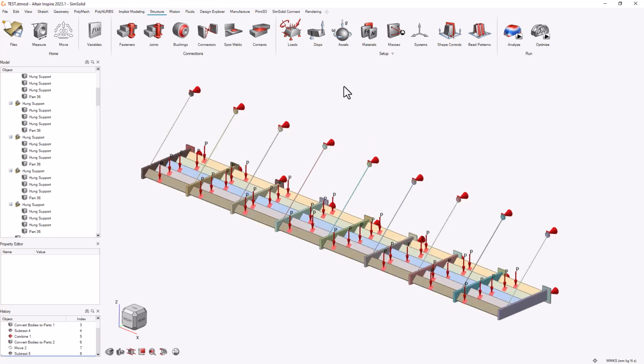Now I'm going to go ahead and analyze this. That was my ultimate intention here, and I'm going to analyze it for deflections and stresses and so on using the SimSolid solver, which can handle this 3D geometry without the process of meshing first. However, if we did want to take a traditional FEA approach, Inspire also allows us to use the OptiStruct solver, which amongst other things can run an analysis, but also optimization and so on using more traditional FEA approaches.